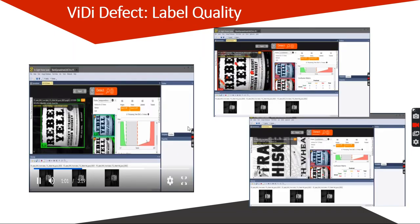Here's an application where we're looking at labels on a liquor bottle. All we had to do was collect 50 good images, and we loaded them through the neural network. Then we created a bunch of bad defects. What happens here is you've got your good images to the right in green, and your bad images to the left. And we've got a very good gap there.